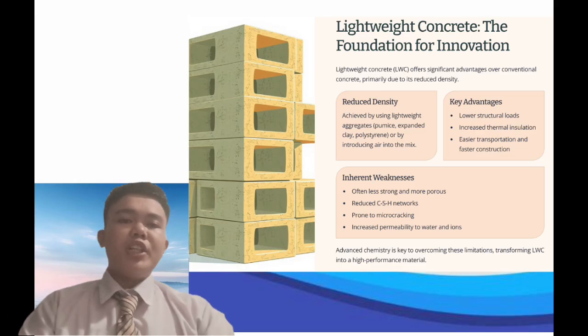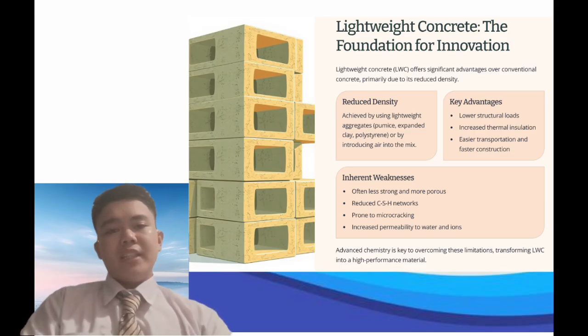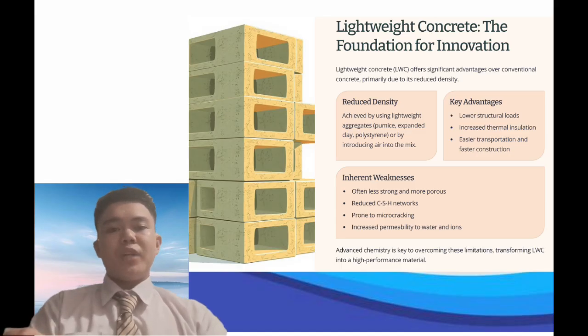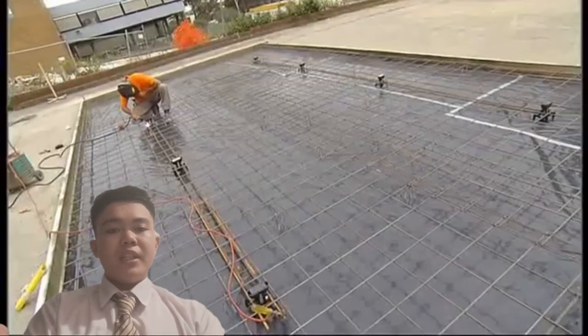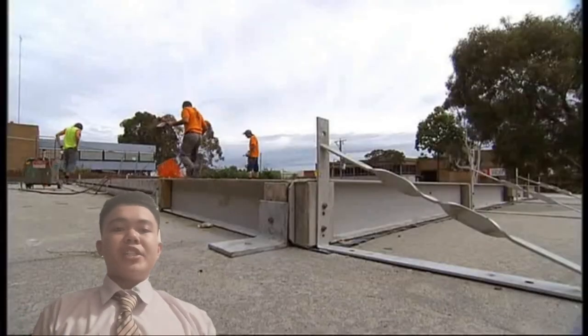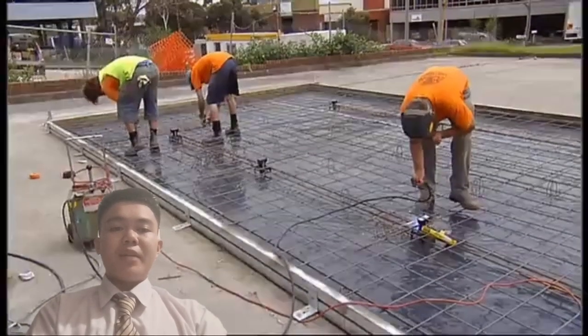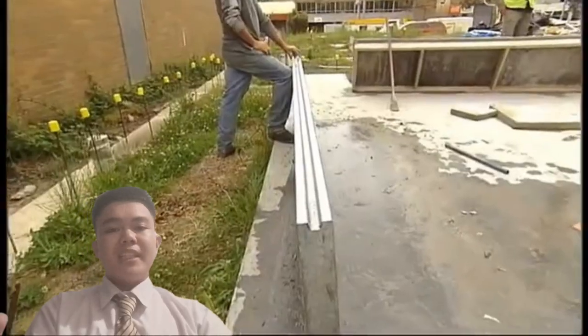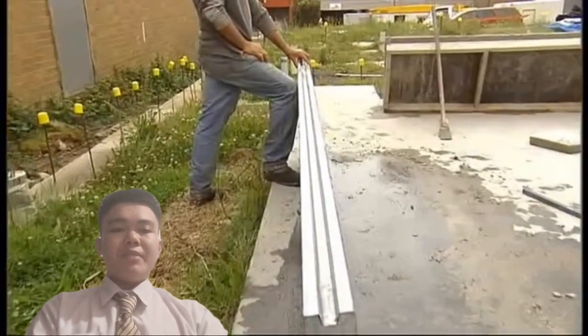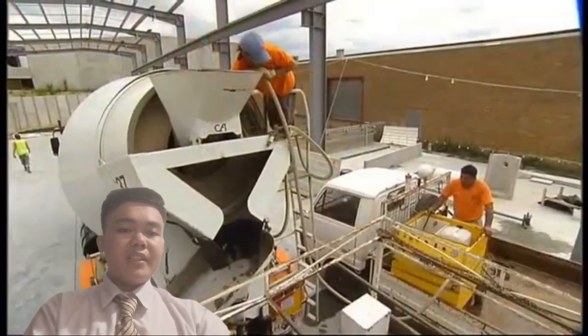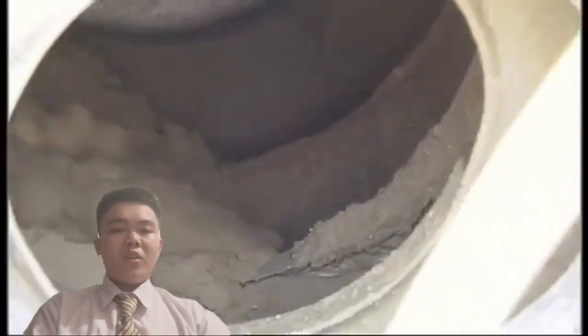There are several airspaces in lightweight concrete. These airspaces diminish concrete strength and make it easier for water and chemicals to enter. This can lead to cracking, corrosion, and degradation over time. We may chemically and physically change concrete to address these deficiencies by adding fibers, microorganisms, and nanoparticles. These additives have an impact on the hydration process, microstructure, and the chemical stability of the concrete.